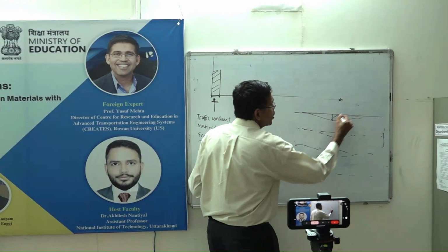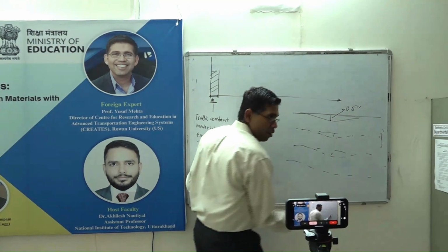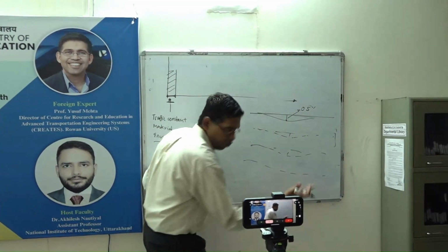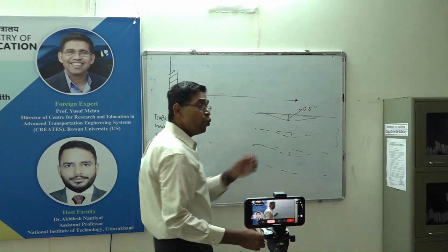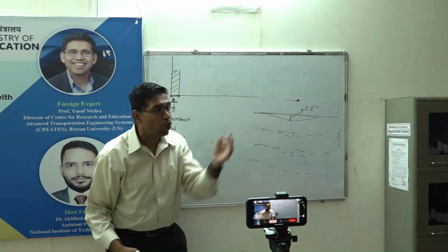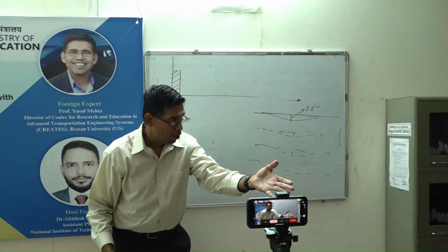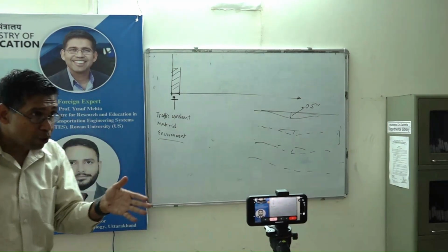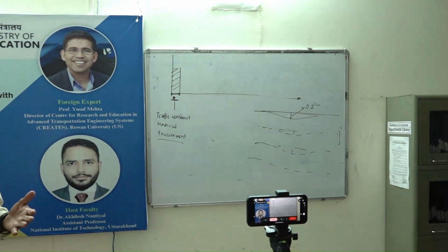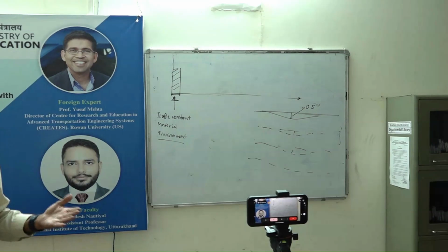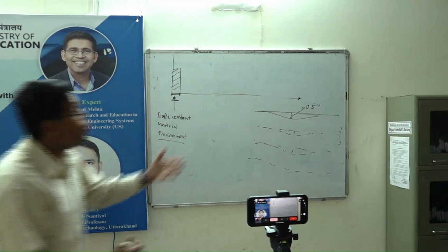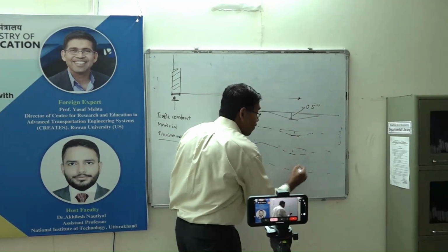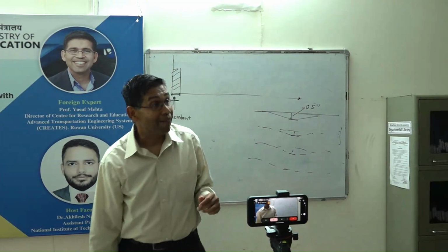So the top is 0.5 inches, let's say. But it could be 0.1 from here, 0.1 from here, 0.1 from here, 0.2 from here. Everybody with me so far? But if I want to exactly know what it is, what do I need to do? Anybody online, if I exactly want to know the exact number, what do I have to do? Yeah, I have to do a cross section. You are 100% correct. You have to cut the pavement and exactly measure that. Correct?